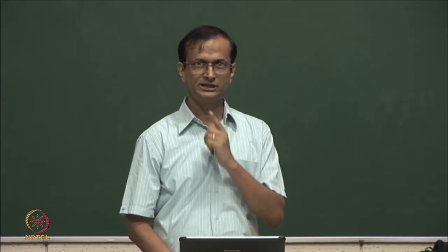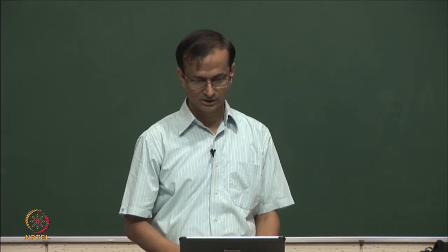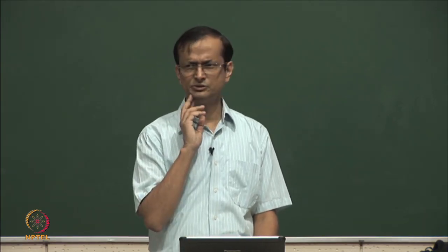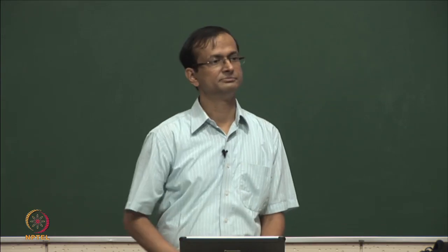On the other hand, if you delay some node that is off the critical path, for which it seems as though some range was there, then you do not necessarily immediately incur a cost. Maybe it can be adjusted later on because some flexibility was there. Some nodes are more flexible, other nodes are less flexible. That is the basic information that one derives from the ASAP and the ALAP. If you do both of them and subtract one from the other, if that number is not 0, then there is some slack. If it is 0, then you have less slack.